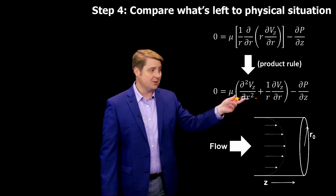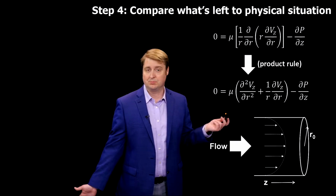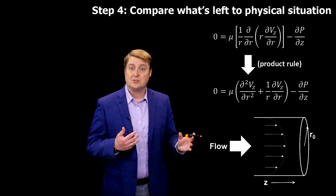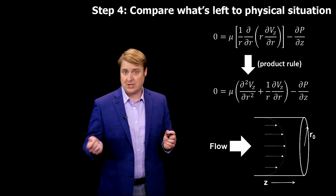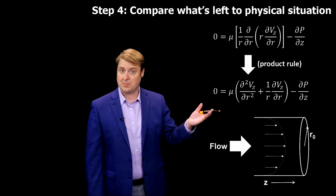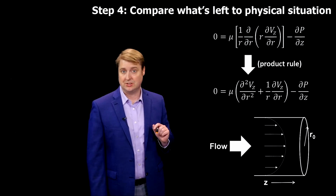Then we look at this next term. Here we have 1 over r, which is non-zero. Of course, our pipe has a radius, so that's going to be a non-zero term. And then we have velocity in the z direction as a function of r. So how does that change? Well, indeed, we do know, just like we were talking about before, velocity in the z direction does change as a function of r. You know, slower at the pipe walls, faster in the middle. So that term is non-zero as well. It should certainly be there.